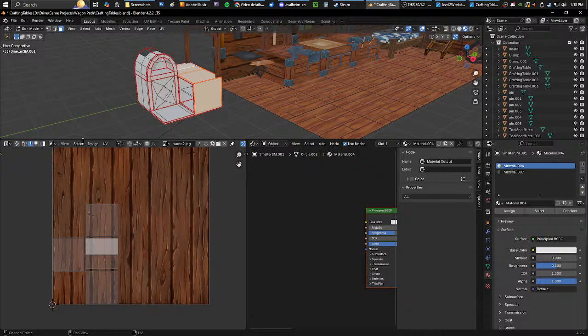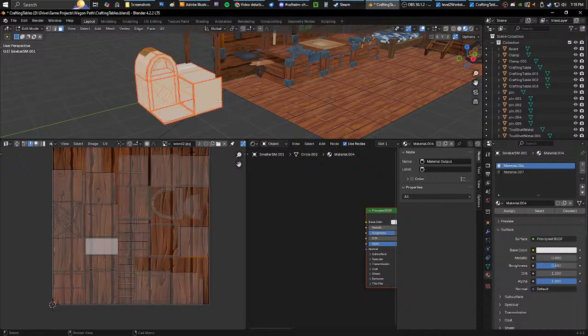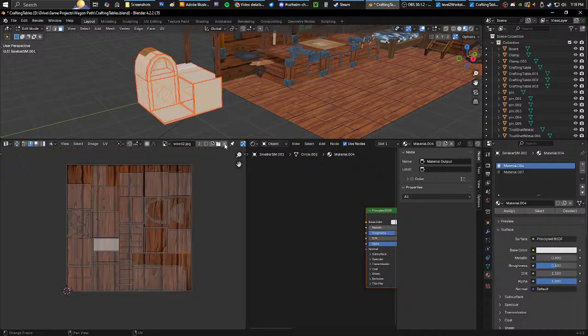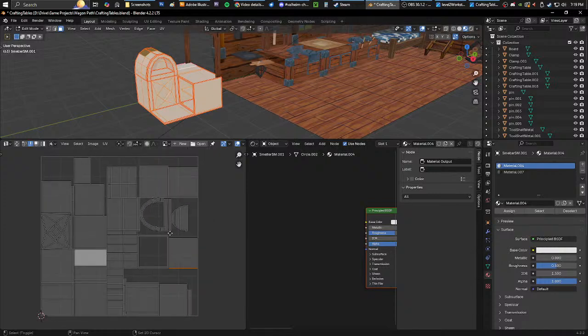You can make one texture, which would be smarter for me to do, just one texture for this model, so it's only having to talk to the one texture when it's trying to render it out, instead of using multiple files to texture this, which is why we unwrap it. That's why we put the seams and make it unwrap so pretty, so we can get this map here.